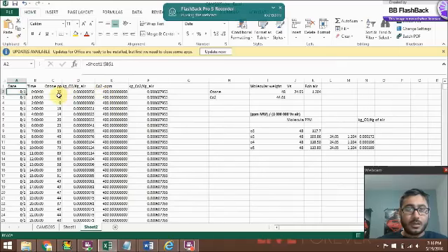So the weather or the contaminant data for Contam is always in the units of kilogram of contaminant divided by kilogram of air. Even though you have your measured data in ppb or ppm, you would have to convert that into kilogram of your contaminant to import it into a weather file. Now this is only valid for exterior contaminants.